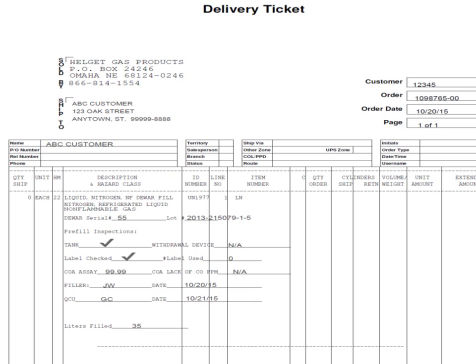The next 3 digits are the reverse Julian date. The next digit is the supply batch lot number. In this case it's a 1, that was the first supply cylinder, D55 if you will, that was filled on the 79th day of 2015.